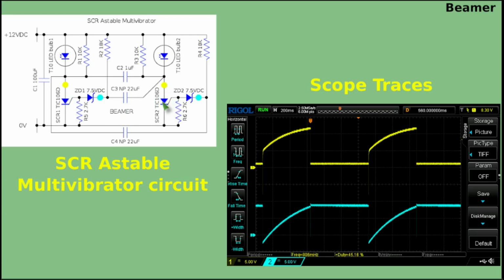On power up, which is always an issue with multivibrators, if all these components were absolutely identical in every way, the SCRs, the capacitors, the LEDs, the resistors, etc., on turn on with a multivibrator, it's got an Achilles heel, and that is that if they were all identical, you could get a race condition that never puts one of these on and the other one off.